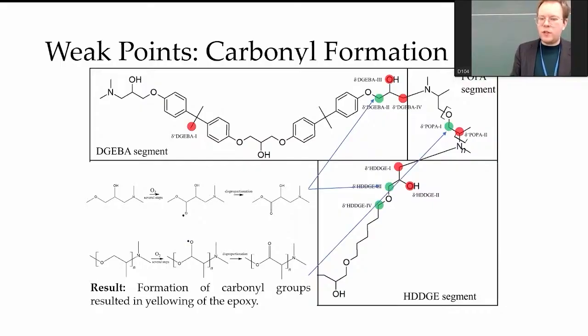Then also, as we know, this is very typically important in art conservation, for example. Epoxy is a glue and is also used in art, let's say, to protect a piece of art. With time, this particular epoxy and most epoxies age and become more yellowish or grayish, so they change their color. The reason for that in this case is carbonyl formation, the oxidation that happens even at quite low temperatures in outside air. It's not by sun, it's not photo-oxidation, this is thermal oxidation.